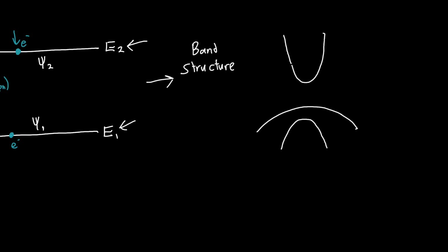So this is what band diagrams often look like in photonics. And we'll go through, don't worry if this scares you. This is an energy momentum diagram. And we'll go over what exactly everything means here, but briefly, energy is on the y-axis, momentum is on the x-axis, and this lets us figure out how electrons and holes, and in particular photons, are emitted and absorbed by